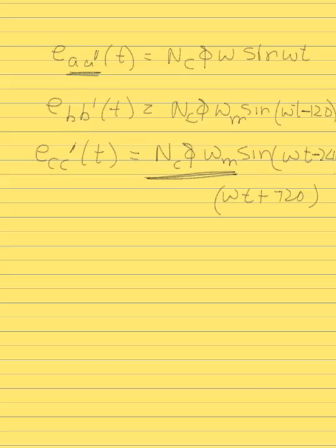So what we realized is that we supply DC current to the field winding of a synchronous alternator, which produces the magnetic field. The component on which the field winding is bound is called the rotor, and this is rotated with the use of an external prime mover. So it results in a rotating magnetic field. Then you place the armature windings inside that rotating magnetic field. It induces the three-phase voltage in the stator, or the armature windings. Since the armature windings are the stationary part, they're also called stator windings.